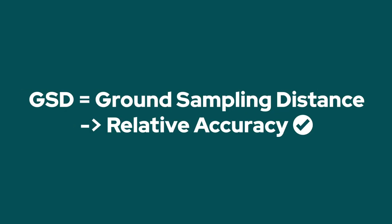Therefore, the thing I want you to take away from this video is that in measurements, how close or far you are from the subject is going to have a bigger influence than some of these other methods that we constantly talk about, things like RTK, GCP, and PPK, which we'll come to later in the video. So proximity to the object is really important, because it governs GSD, and GSD is what governs the relative accuracy.